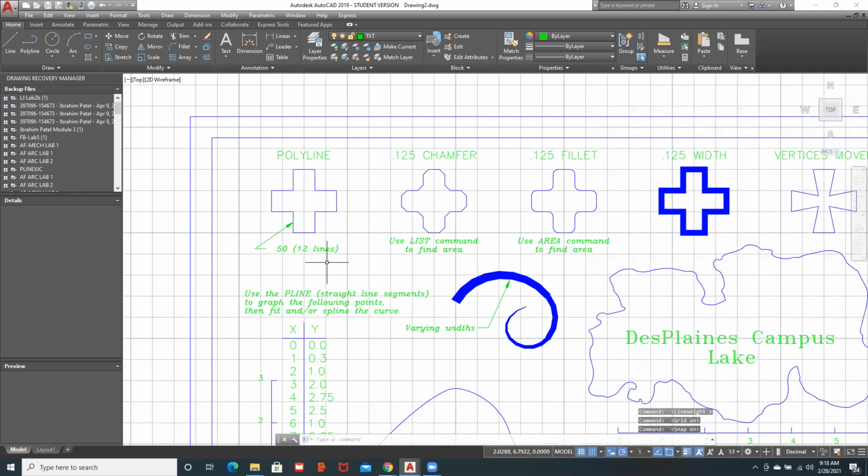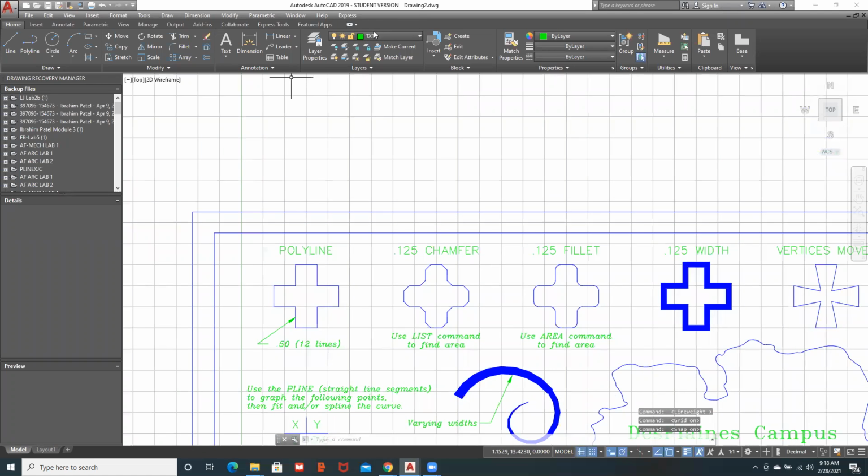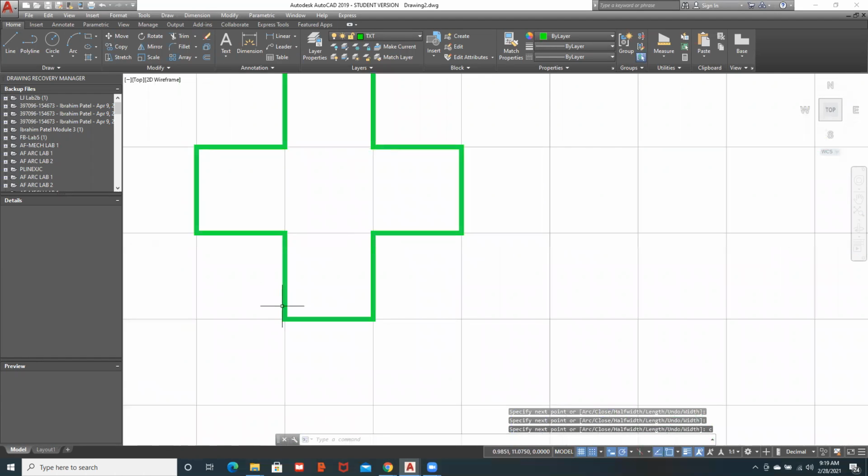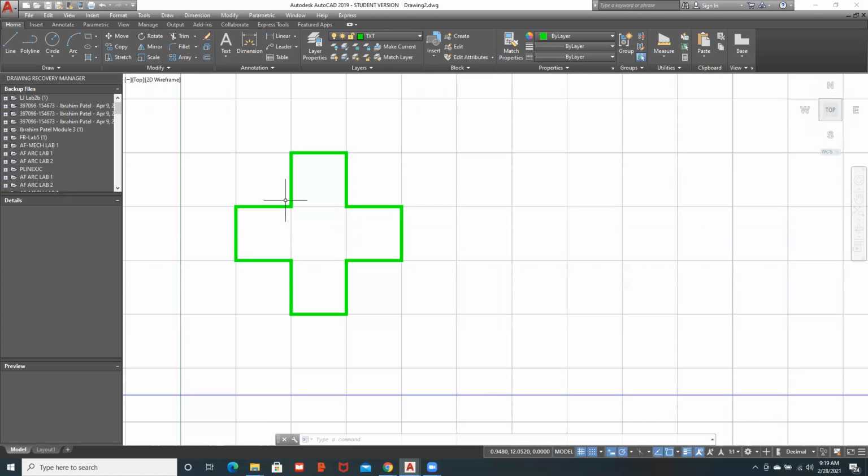And so if I put on a grid and a snap, and I create something with a polyline, I'm just going to create it on this text layer. It's fine. And then when I go through and create these geometries, I'm going to type C for close here. It's better to type C for close, because otherwise there's a seam. You can actually see it.